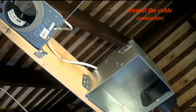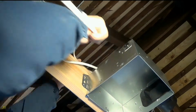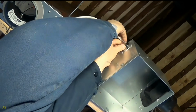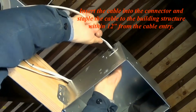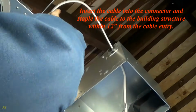Install the cable connector. Insert the cable into the connector and staple the cable to the building structure within 12 inches from the cable entry.